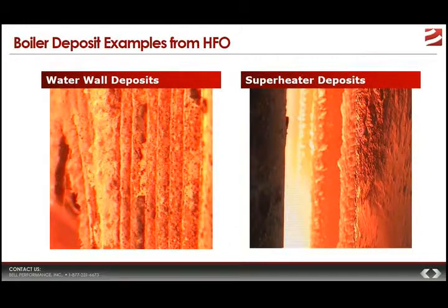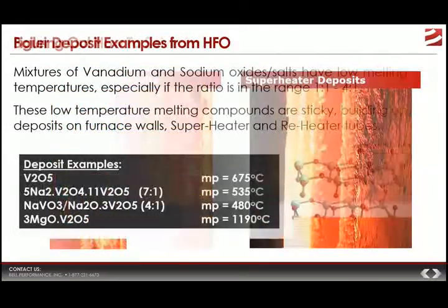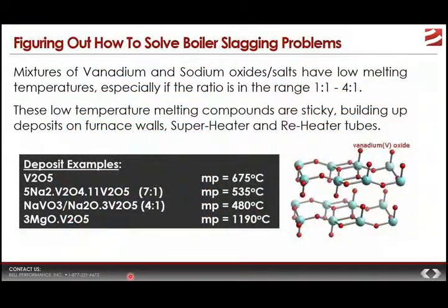These look like pretty serious deposits that the operators in these plants really are going to have to figure out what they want to do with. So, problems for HFO users arise in part when deposits with low melting points are formed. When the fuel oil has the wrong mix of vanadium and sodium, that can mean that the metallic composition in the resulting deposits will give you low melting point slags that build up on metal surfaces.